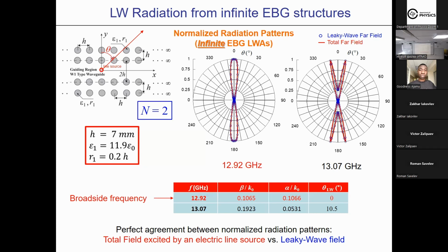However, when we have some disagreement between the propagation constant and the attenuation constant, we have a typical leaky-wave characteristic, not broadside radiation, but a kind of scanning toward infinity. But still, we have a very good agreement between the results, which are based, of course, on the method I proposed, and of course, beta and alpha calculated using the Lattice-Sum approach here, and using the leaky-wave analysis here.